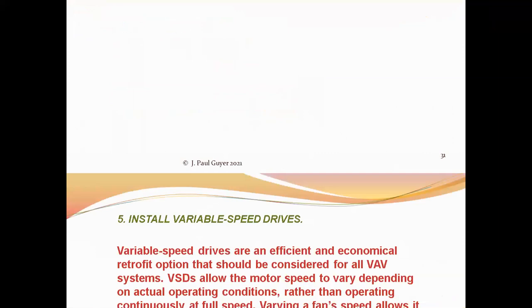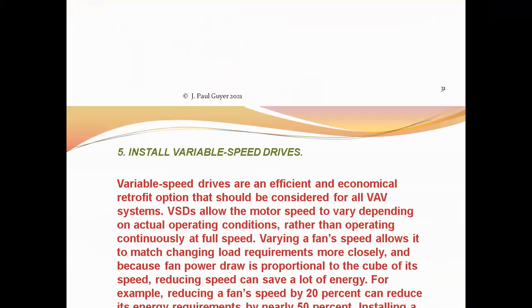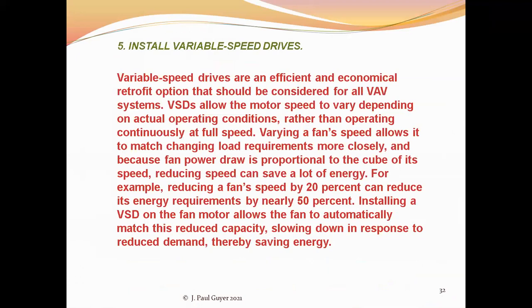Estimating the savings, that's a fairly detailed piece of work that involves the operating schedule for the system, the type of flow control, the duty cycle, the new motor horsepowers and efficiencies, peak flow rates, peak cooling coil loads.